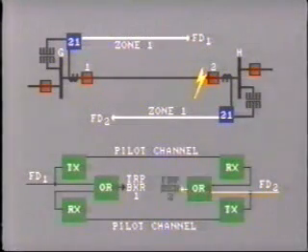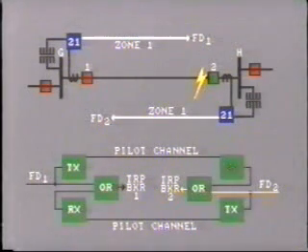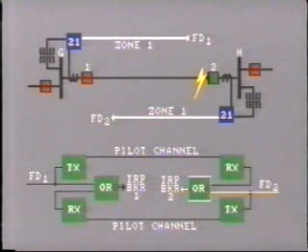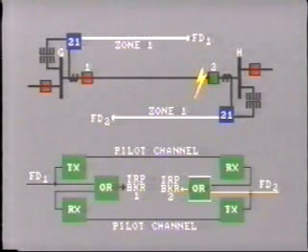The signal passes through the box and goes on to trip breaker number 2. The OR designation means that the breaker will also trip for a signal coming in from the receiver. Either one of the signals will cause the breaker to trip. That is one or the other. At the same